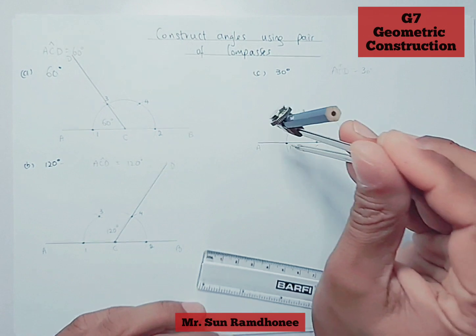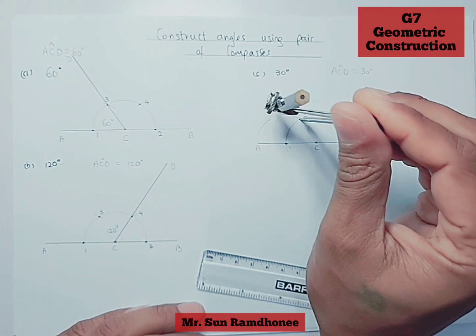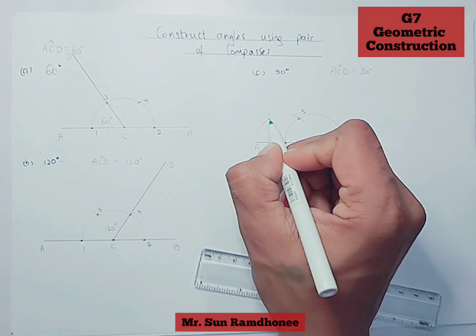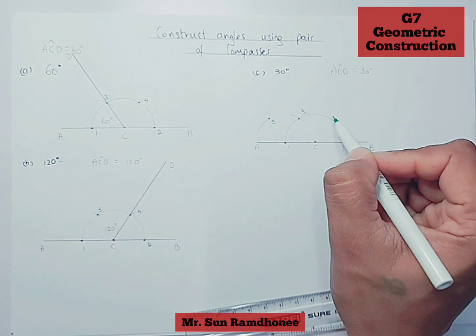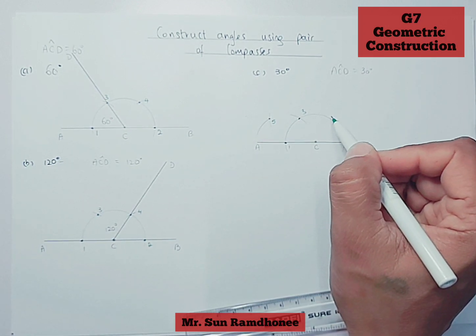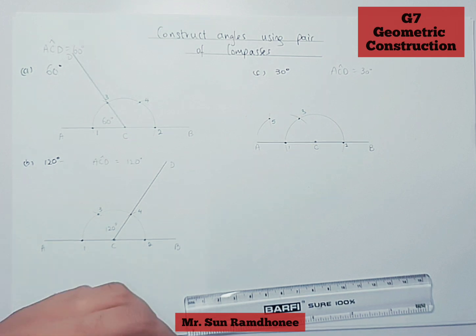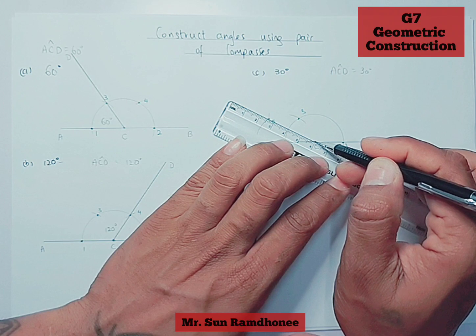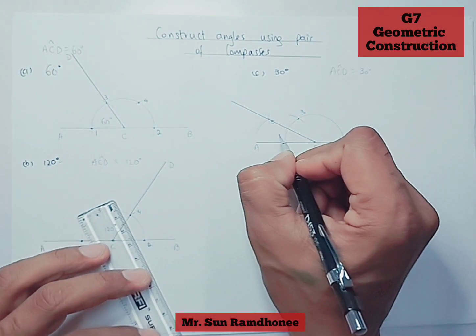We're going to use point 1 and point 3 to draw 2 arcs. These arcs will give us point 5 because we assume that point 4 is here. Once you have obtained point 5, what we have actually done is that we have bisected this angle of 60 degrees using point 1 and 3. This is how you obtain 30 degrees.